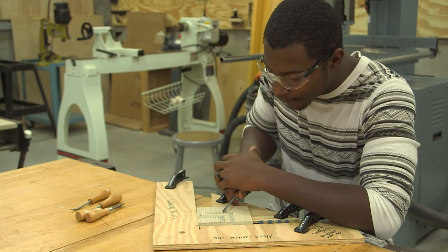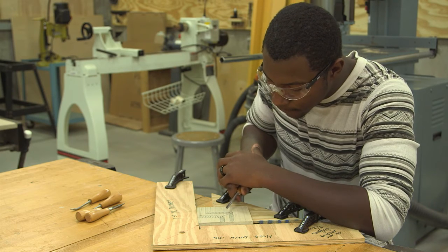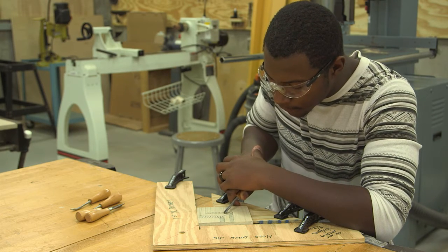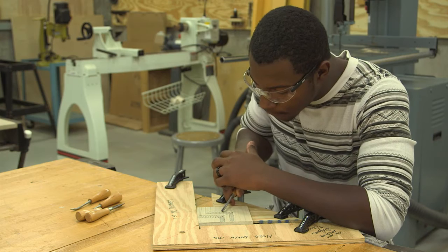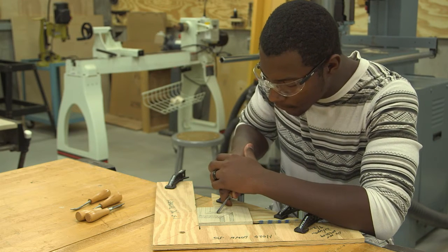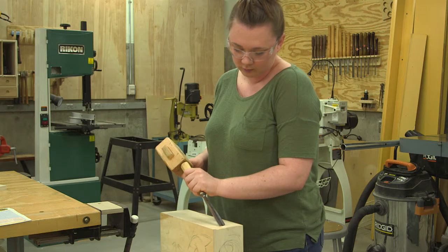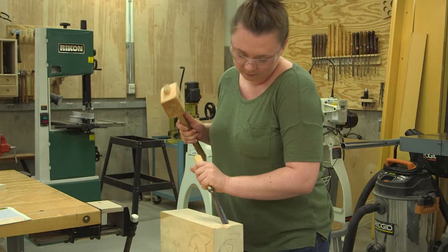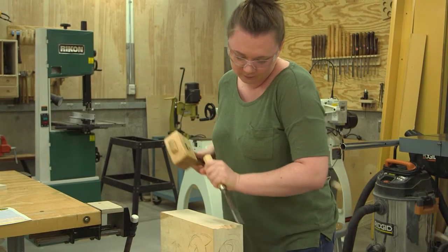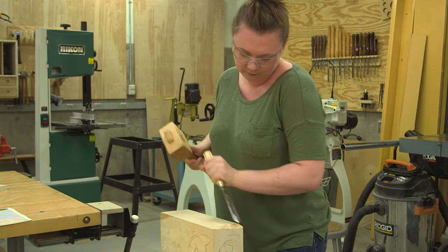The first step in starting your project is deciding what tools are most appropriate for the design you're trying to achieve. If you are trying to create an intricate design on a small piece of wood, you should use the palm tools, which do not require a mallet. If you are removing large amounts of material to rough out a form, you should choose a large U-gouge, which will require a mallet.